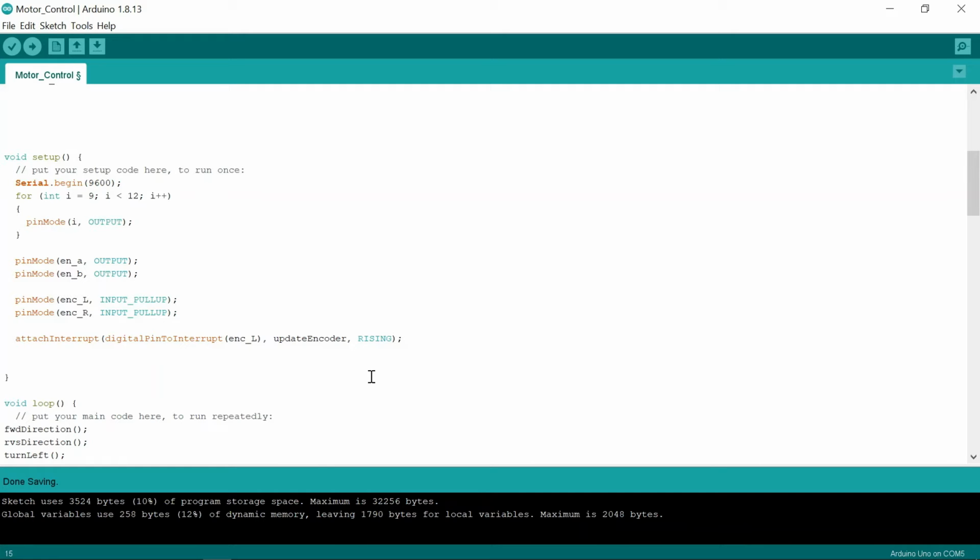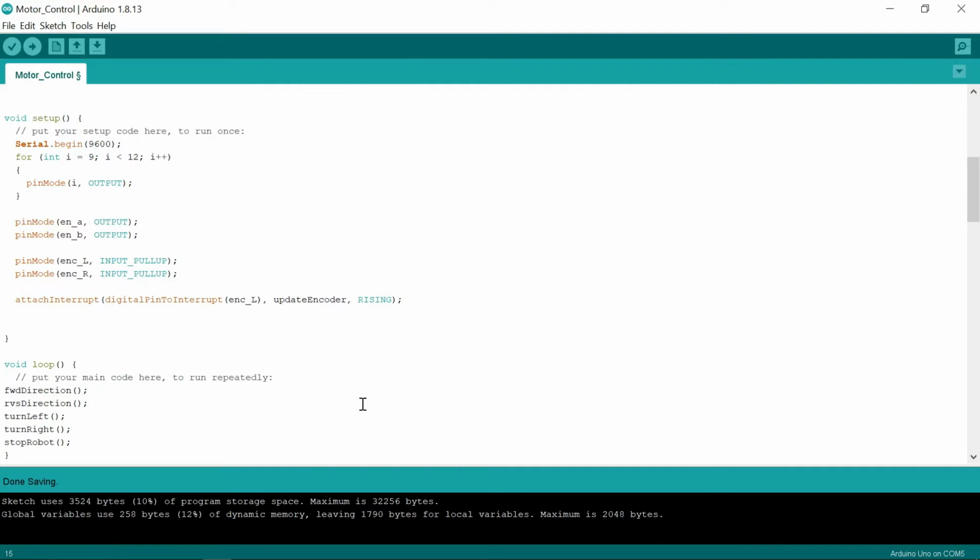So what happens is there's an interrupt, and every time this thing hits a stator vane, it is going to turn off, and then when it opens back up, it turns back on. In other words, think of a wheel with spokes on it. Every time this thing sees a spoke, it closes, and when it gets past that spoke, it opens up. That's the best way I can describe it to you, and that's how it works.